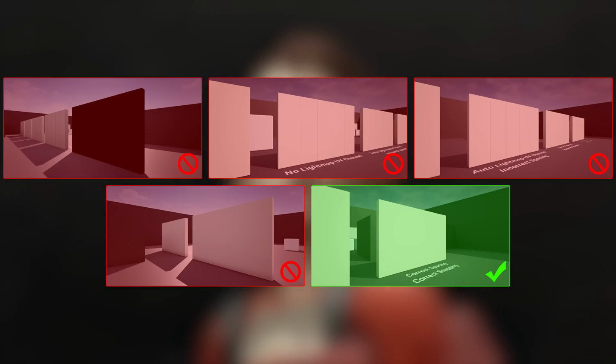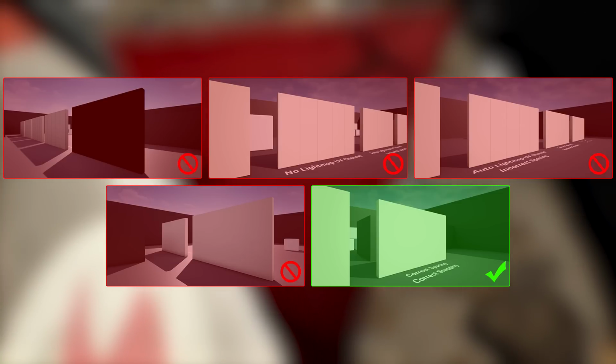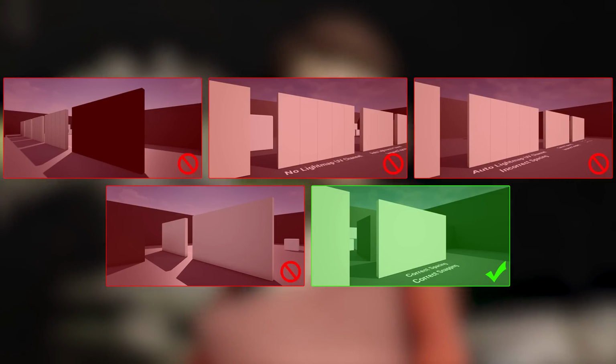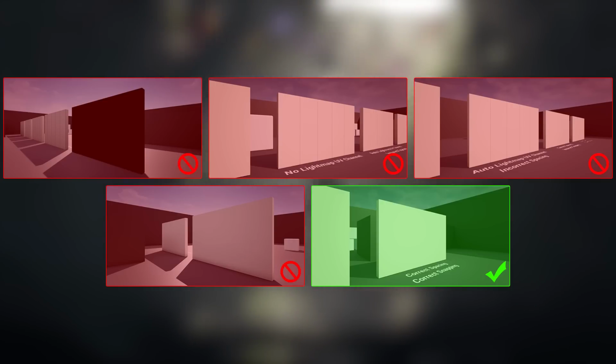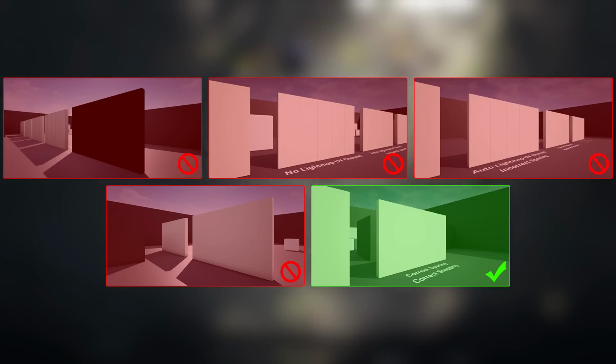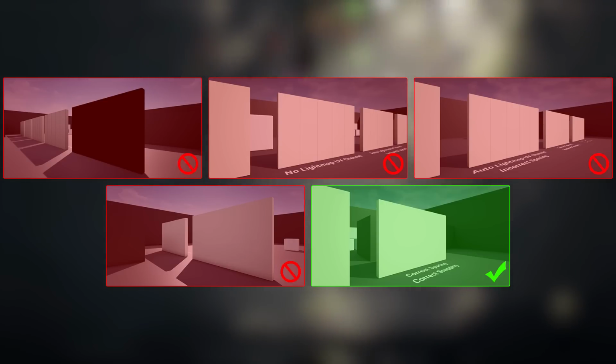Before I demonstrate the correct way of UV mapping a lightmap within Maya, I thought it might be beneficial to show some examples of incorrect lightmaps and how they appear within the Unreal Engine. Each example is comprised of 5 modular meshes, which are intended to appear as a single seamless wall structure.